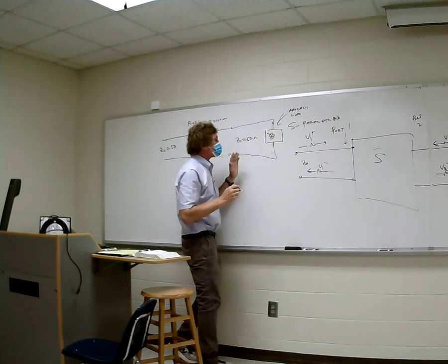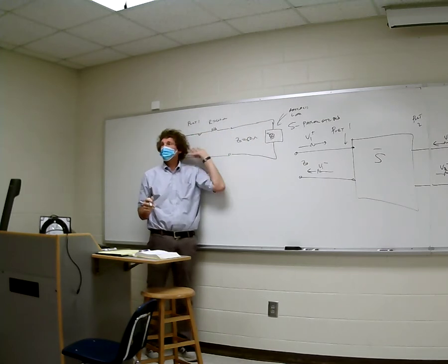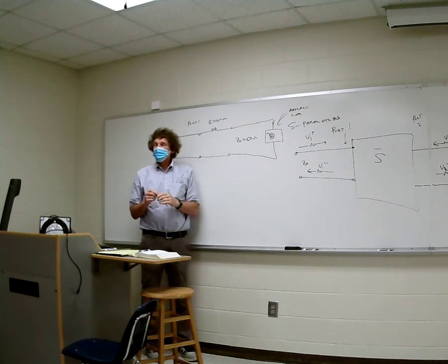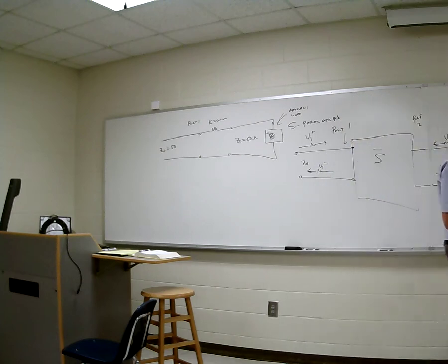Now the only reason I did that is now nothing's going to be reflected. If something gets through here and hits, it doesn't reflect back. It's called a matched load. Y'all follow me on this? Whenever you hear the term matched load or matched port, it means V2 plus is 0. There's nothing coming back. That's all it means.